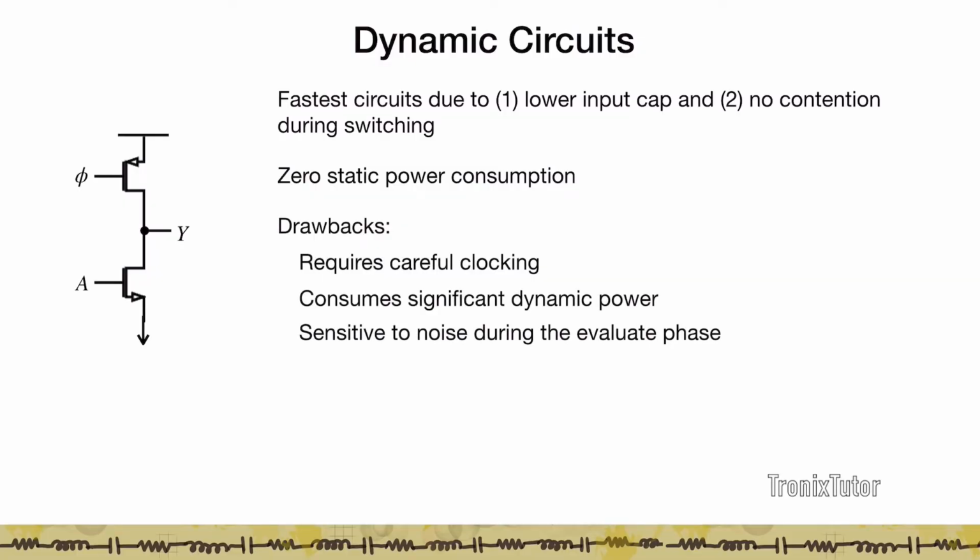Now, the drawbacks of these kinds of circuits: obviously there are quite a few, and this is the reason why they fell out of fashion except for a few applications in the SRAM. One, they require very careful clocking. Two, they consume significant dynamic power because all the gates have clocks, all the gates have capacitance, so every time you have to push the capacitances in and out. And finally, they're very sensitive to noise during the evaluate phase.